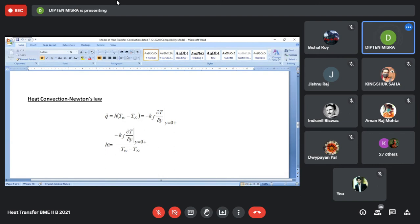One way can be through a theoretical approach. If you can equate these two, we can say h is equal to minus k del T del y at y equal to 0 plus, divided by the temperature difference between the wall and the free stream temperature.